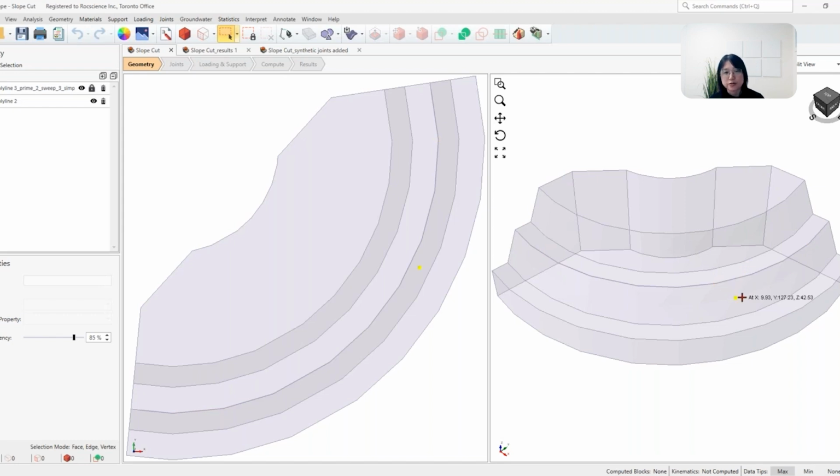So this is where we can use Dips. The second question is, can there be different scales of failures? Can there be crest failures, failures on the walls, or perhaps a larger inter-ramp failure that can pass through the multiple slope cuts or benches? Okay. So let's process our linear traverse data first and see what we can do in this case.